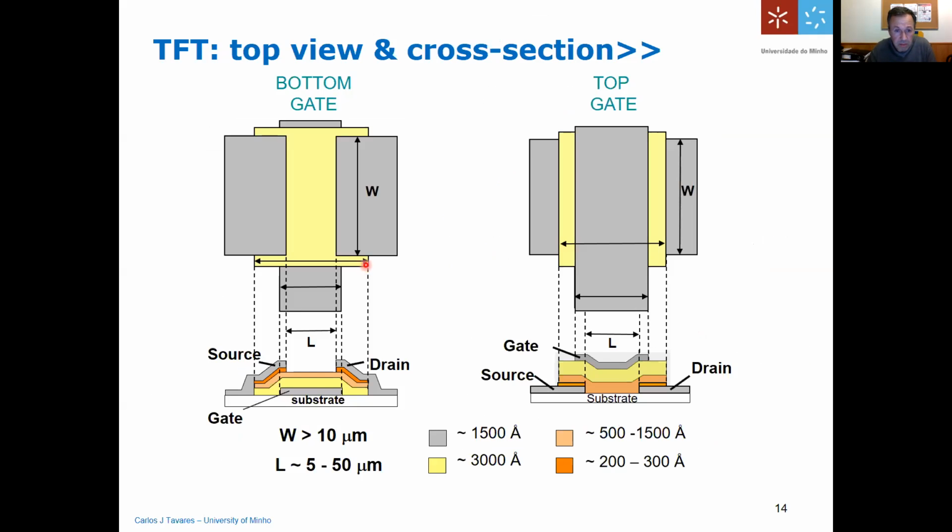Here you can take a closer look and see how it looks from the cross section and from the top. So you will have your substrate, okay, and all the layers that you will put on top. You will have an idea of the thickness of the layers. Normally the aluminum metal contacts are around 150 nanometers, or 1,500 angstroms.